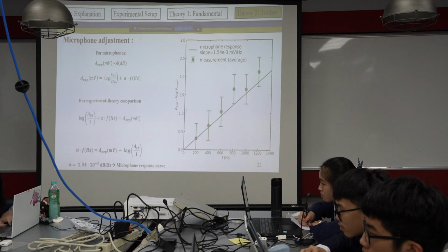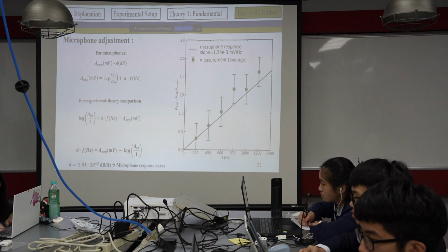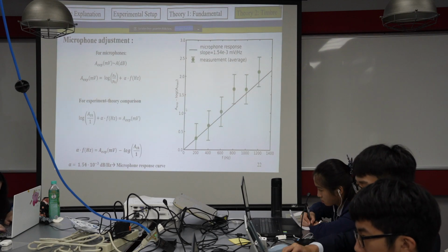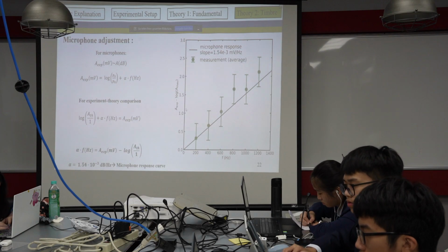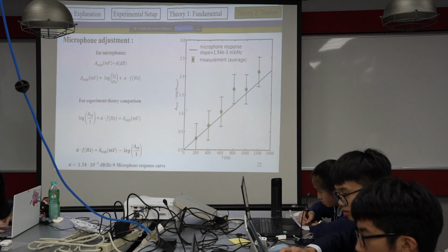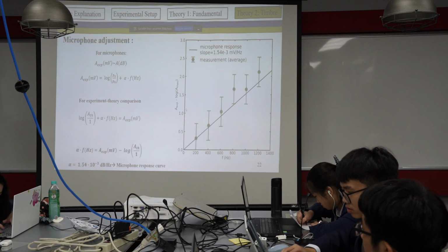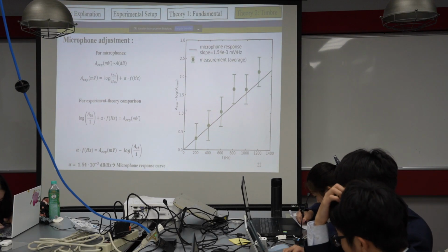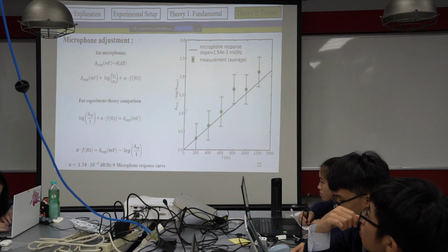The amplitude of the experimental data, in our case, is directly proportional to the amplitude in decibels. This means that the experimental amplitude is actually the logarithm of the measured pressure divided by nominal pressure and adjusted by a factor alpha that is frequency dependent. A factor alpha like this is used in almost all microphones and is actually to adjust the amplitude of the sound to the human ear.